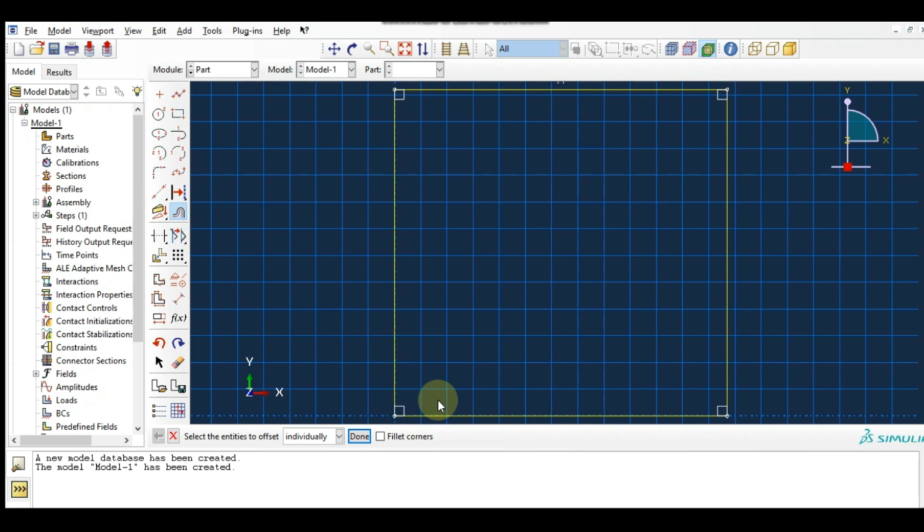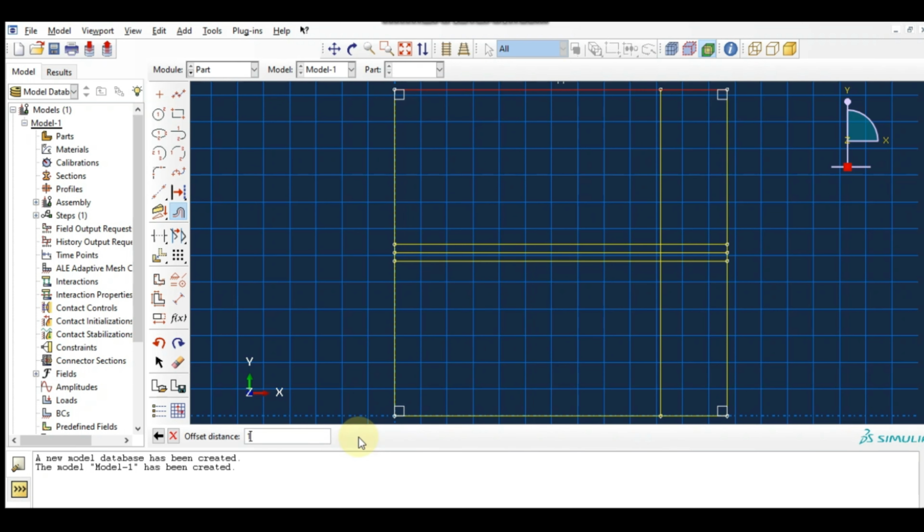Now creating the bottom line for the offset, click the offset of the bottom line, which is 28.8925. Now by clicking the new offset line, make the offset again, 1.5875 and 3.175. After that, click on the vertical line for the offset, which is 12.7, and after that we choose the above line for the offset, which is 16.5.